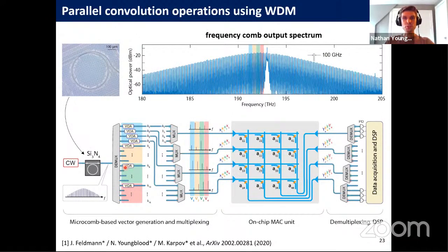So a very cool feature of using optics rather than electronics to do this is the ability to multiplex computation in frequency space rather than in time. So in collaboration with Wolf Bernice's group at the University of Munster and Tobias Kippenberg's group at EPFL, we've demonstrated this multiplexing concept using an on-chip frequency comb shown here with hundreds of independent wavelengths as our broadband light source. Here we can use 4 different wavelength bands highlighted here to perform 4 matrix vector multiplications simultaneously in the same physical core.